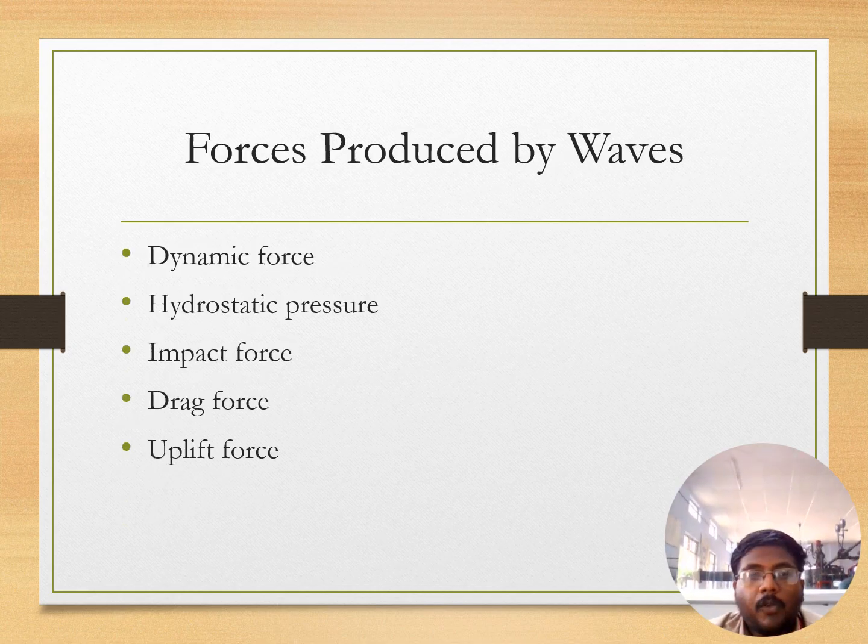Next we see about what are the forces produced by the waves. In general, what is meant by waves? Waves can be generated with the help of water. Five different types of forces can be generated. They are dynamic force, hydrostatic pressure, impact force, drag force and uplift force or buoyancy effects.